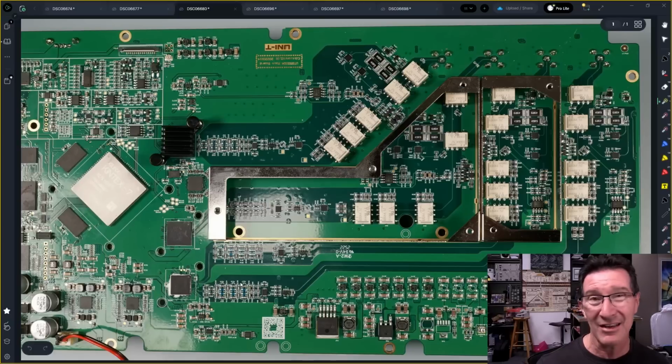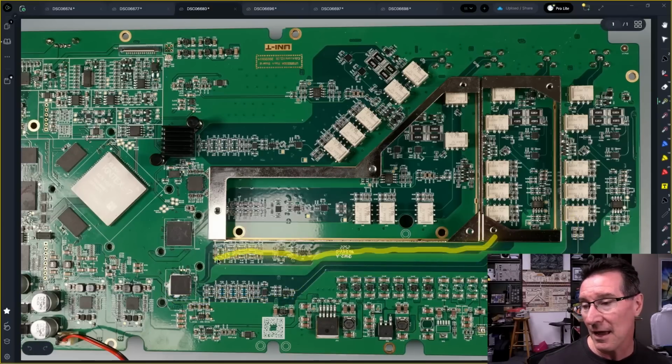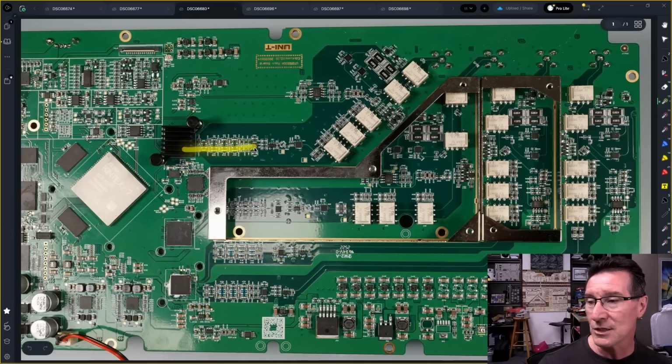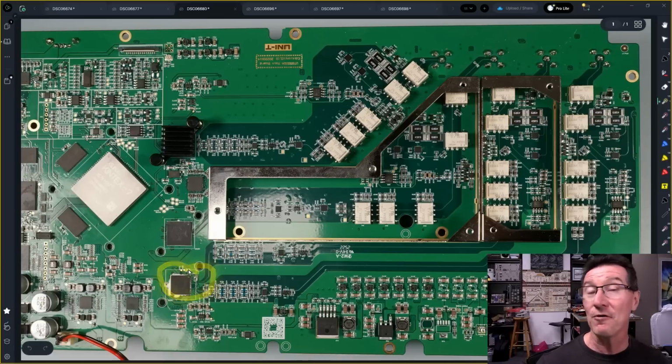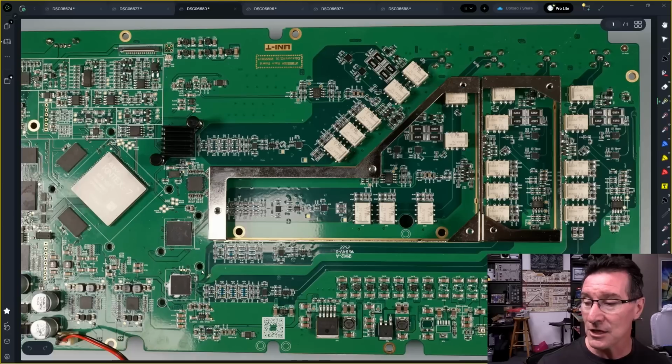This is not a teardown analysis, really. It's more of a BOM analysis. And you can see that both of these come from this DAC over here. And you can see that there, like that. Whereas these two have their own dedicated DAC, 2.5 gig samples per second, channels 3 and 4, because they have lower bandwidth and lower sampling specifications, they're sharing a DAC down here. And as you'll see, curiously, they're a different manufacturer, and these are not what I expected.